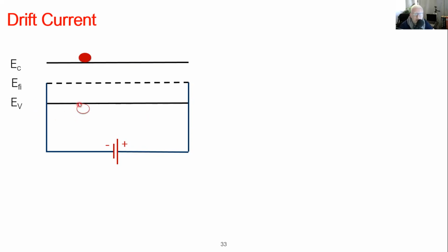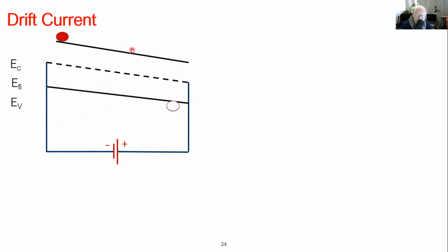In order to demonstrate this attraction effect on the energy band diagram, we should make what's called the tilting effect. This tilting effect means that, applying the minimum potential theory, my dear students, the electron will act to go to this place because the potential energy of the electron here is lower than here. If you remember, we mentioned in part number 2 that the electron energy increases upward. So this state has a higher potential energy with respect to this state. So the electron will act to move to the lower potential state.